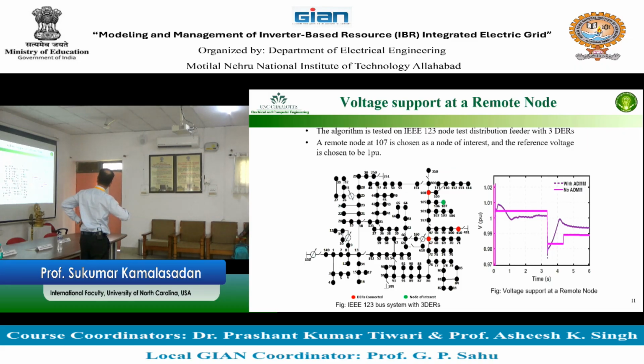So how can the coordination be done? In the inverter sense, it is not difficult because this works very fast. Reactive power, this is like 80 seconds. Remember 70-80 seconds we talked about. So there is a time scale separation. If you take care of the time scale separation, for example through Nyquist or some other, like 80 divided by 10, so within 7 seconds the inverter is pushing the reactive power, then we are safe. We have a time scale separation. Then you don't need to do any communication device and connect and things like that.